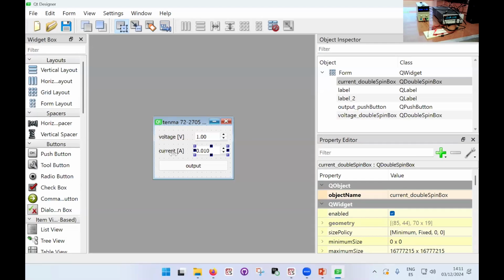It will limit its own voltage internally, so that the voltage actually being output is not the one that I asked for, it's the one that is required to reach a current of 20 milliamps. So if you're below that limit, then it acts as a constant voltage supply. It will output the voltage that you are asking for. So in my case, from the specification of this LED, it's a very small LED.